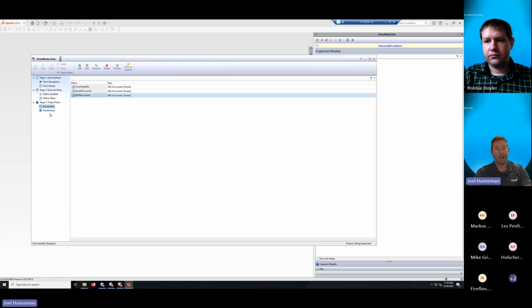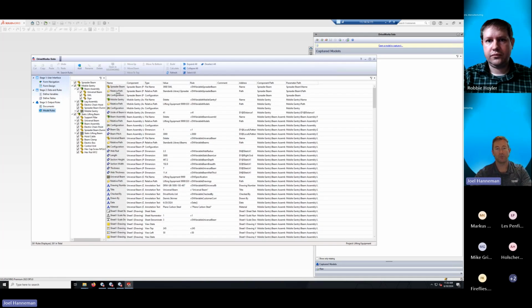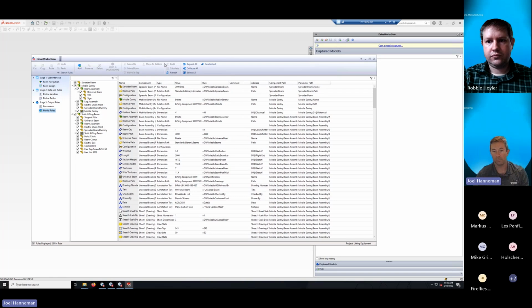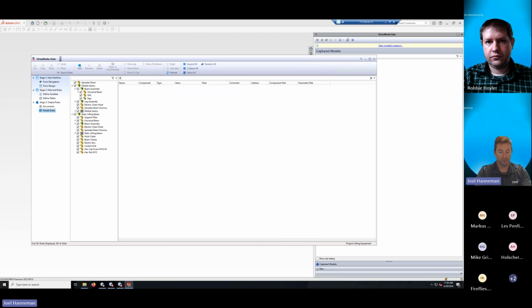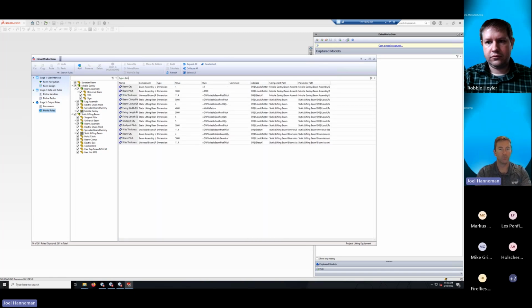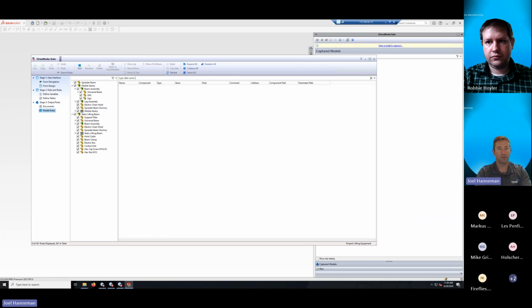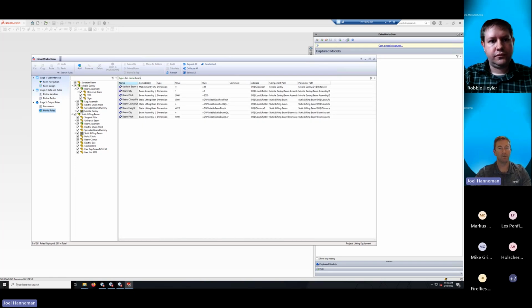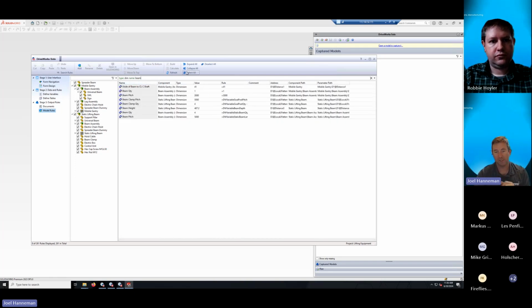And additionally, the next most obvious thing is the space in which we create the rules. As opposed to doing that directly in SolidWorks before, we can now do something like this, where we take all of our dimension rules for something to do with a beam. Here we go. Just like that, we can collect and present to ourselves every piece of information routing that will go from DriveWorks to SolidWorks and look at it and consider it all together. Some of this stuff is simple, like it's just a number.